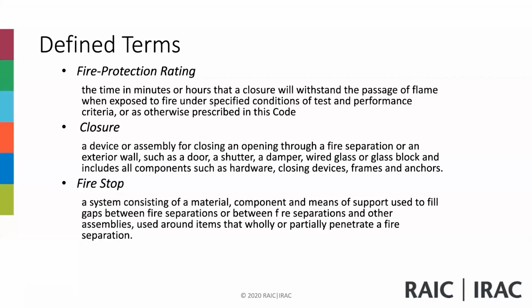There is a glazing that is fire resistance rated. So you have to make a difference between the fire protection rated closure glazing, which is glazing that is tested to the closure test. And we'll see what the tests are that are applicable for closures, and fire resistance rated glazing, which is tested in accordance with fire resistance requirements.